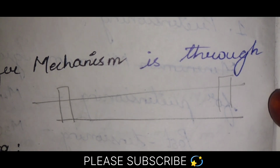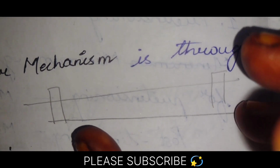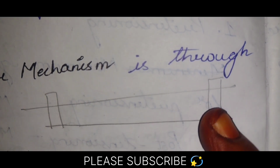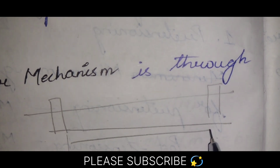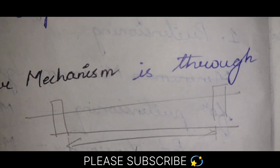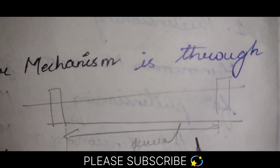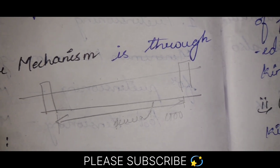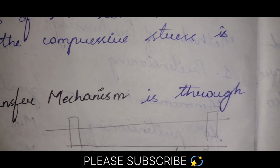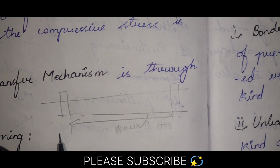Whenever we are talking about the long line process, the tendons are stretched between these two bulkheads, several hundred meters apart, like 800 meters, 500 meters, depending upon the requirement and the space we are having. So the tendons are first stressed.